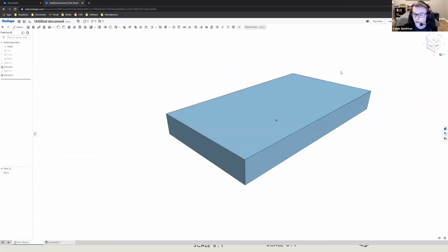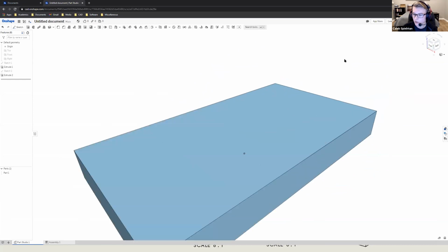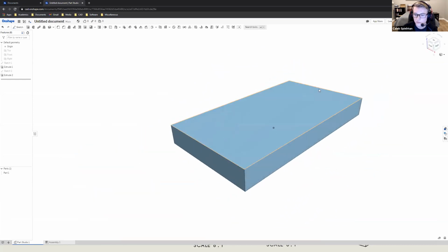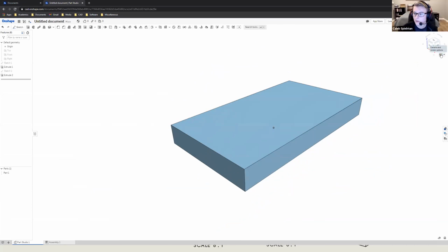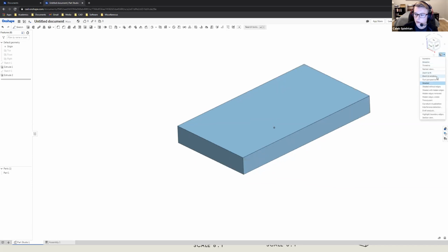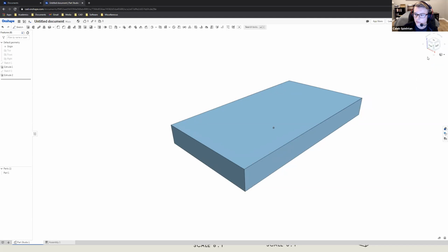I know that I've used SketchUp and it actually does look something like this. So how did you turn that on? You right click something. Oh, that one. So right here next to the viewing cube, there's another cube. It's just the camera and under options, there are several options. And here I can just turn perspective off. Or I can turn it on.